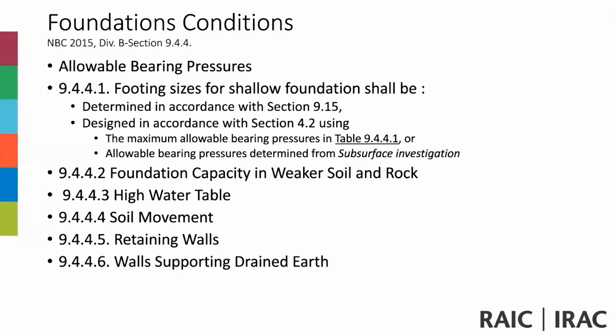So similar to structural elements where we're doing design loads, we can use Part 4, but when we're using Part 4, we can actually use the maximum allowable bearing pressures, maximum allowed design loads from Part 9. Or for footings, for shallow foundations, you can use the allowable bearing pressure as determined from subsurface investigation.